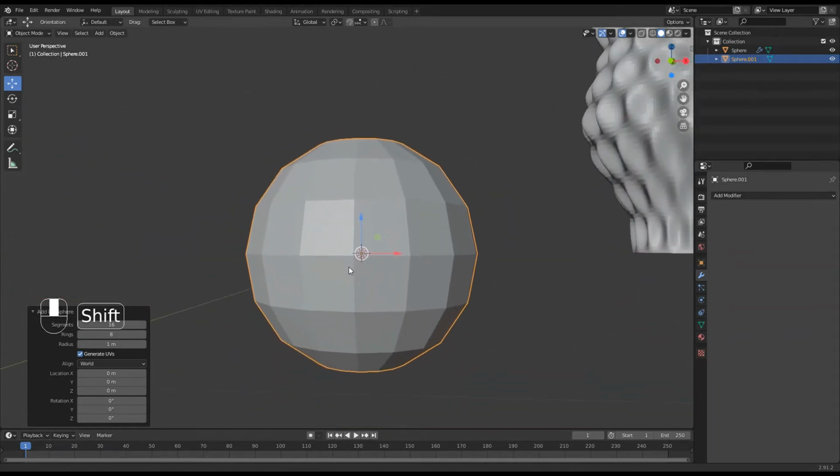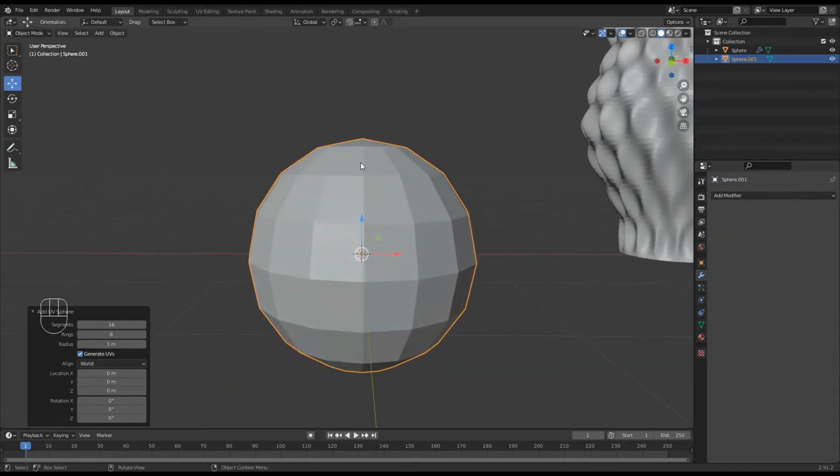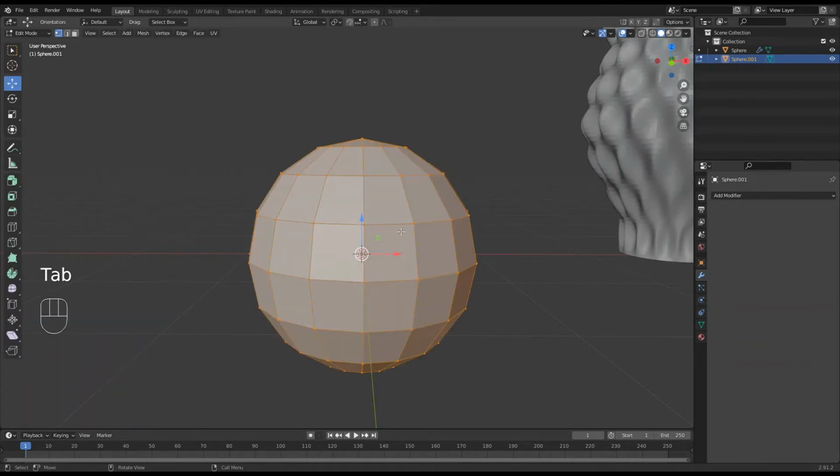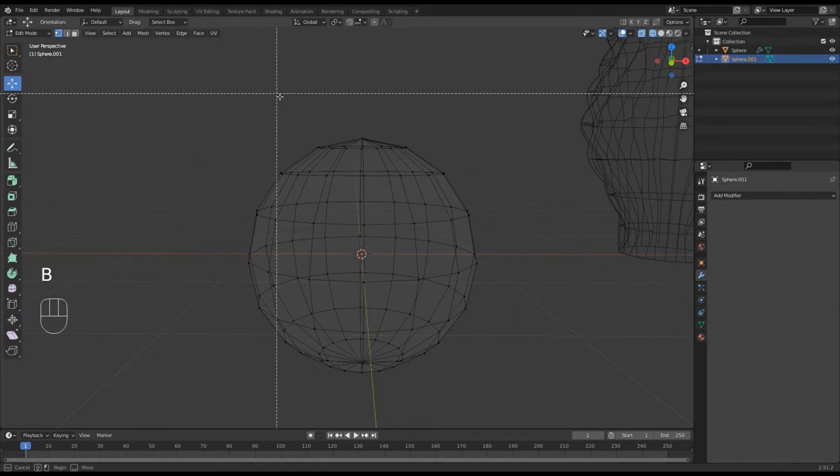Right. Now as last time, I'm going to chop off just the top and bottom. Let me go into edit mode, and I could go between the wireframe and solid view up there, but I also know that if I press the Z key just on its own, I get this wheel coming up, and there's solid and there's wireframe, so it saves me having to go up there. I can just do it with the keys. Okay, and box select that lot.